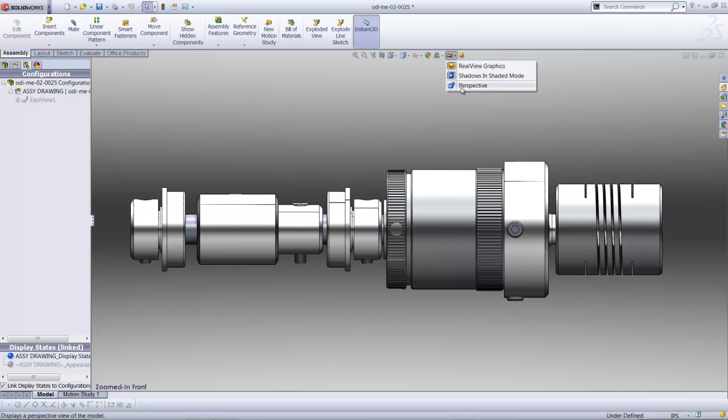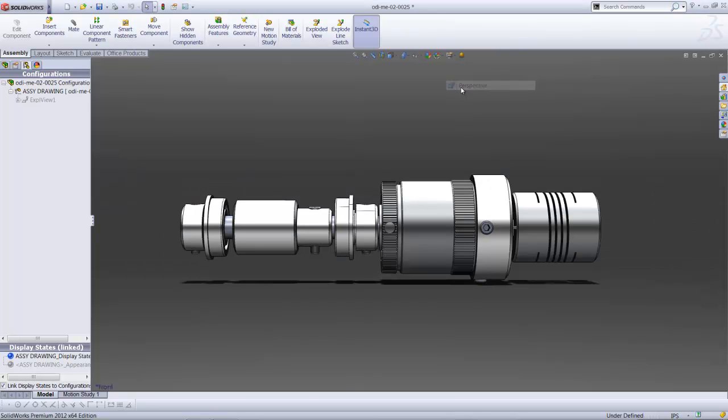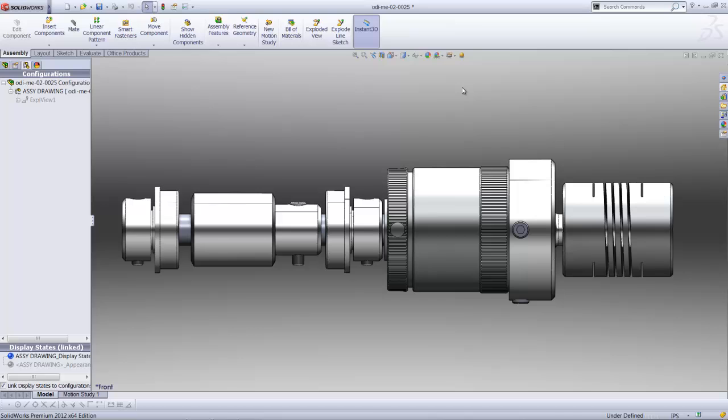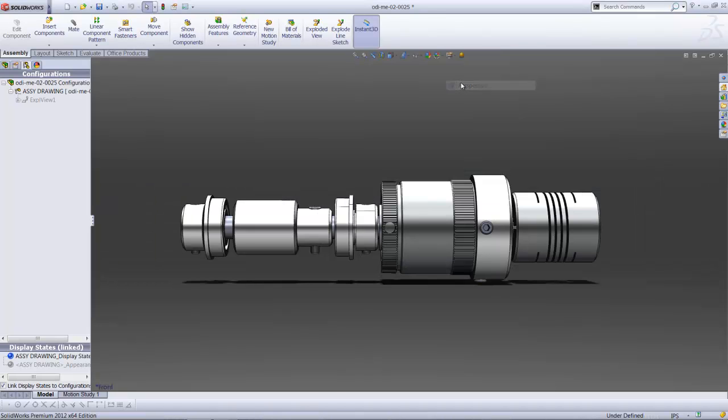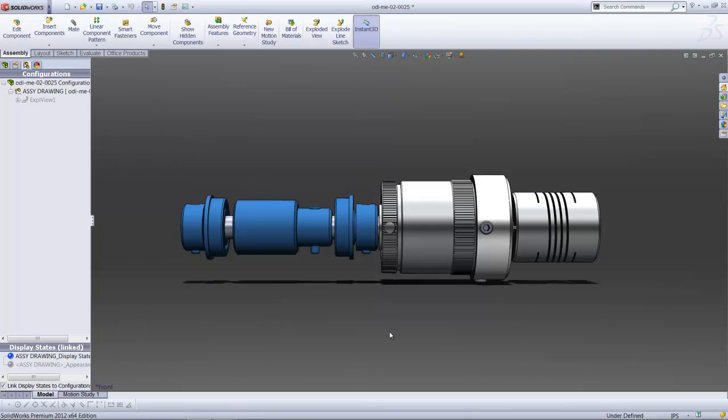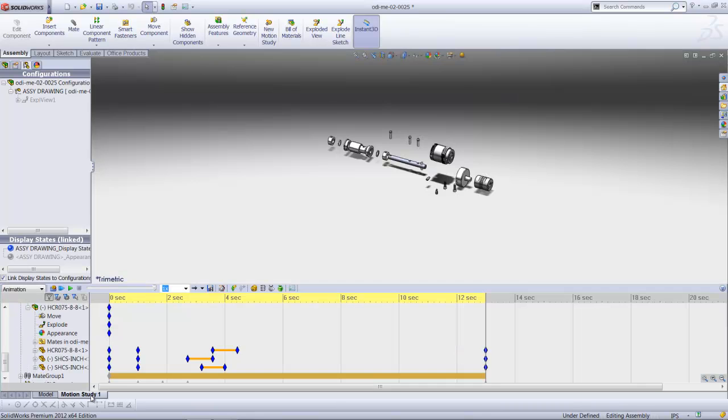One last thing we always overlook is perspective. When creating a video, perspective also helps. So this is with perspective on, this is without perspective, and that's how things look right now. Now one of the reasons why I turn on perspective towards the end is that the dragging to window select items doesn't exactly work very accurately with perspective. Just a slight troublesome spot there to consider. So what I like to do is just turn on perspective at the end of everything.